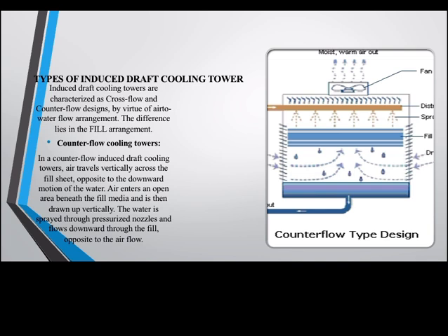So we have the air entering this small opening beneath the fill media, and it is going to be drawn up vertically. The water is sprayed through pressurized nozzles and flows downward through the fill media opposite to the airflow.